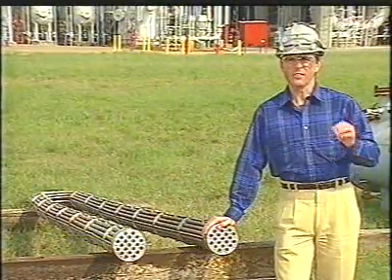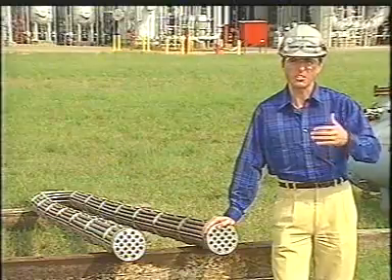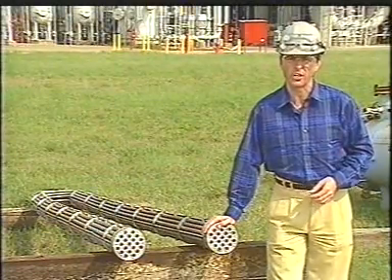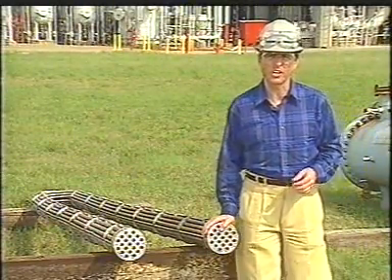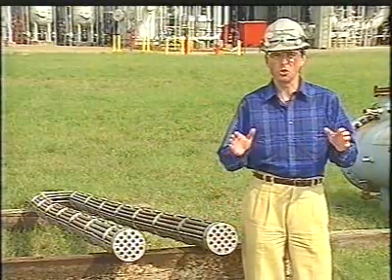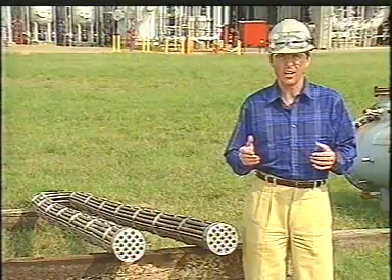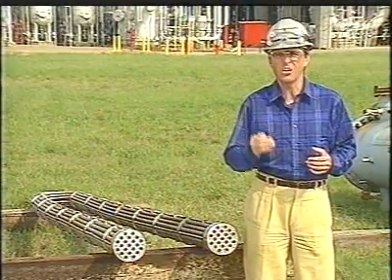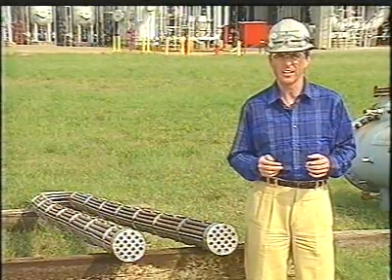In this type, the tubes are free to expand because they're only attached at one end of the tube sheet. So a U-tube exchanger can handle fluids that vary greatly in temperature. Although the U-tube bundle can be removed from the shell, the bends in the tubes hinder internal inspection and cleaning.